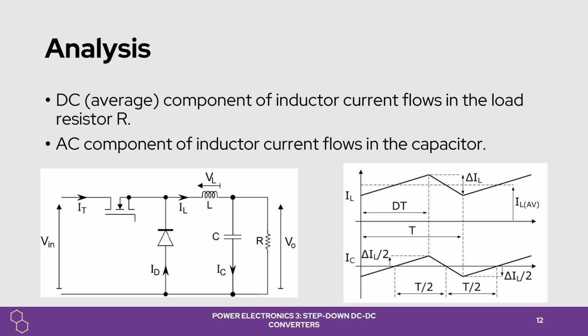Here we analyze how the current for the capacitance works. When the capacitor current is positive, the capacitor is charging, as we can see in the bottom figure. It starts charging because the current is positive in the inductor, and the total current is positive. So the capacitor starts charging, according to the definition of the capacitance.